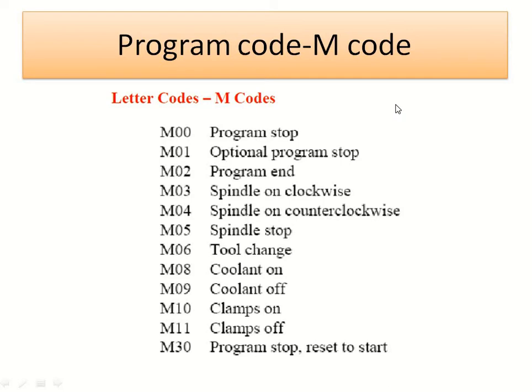Program code letter M, the miscellaneous functions: M00, program stop. M01, optional program stop. M02, program end. M03, spindle on clockwise direction. M04, spindle on counterclockwise direction.